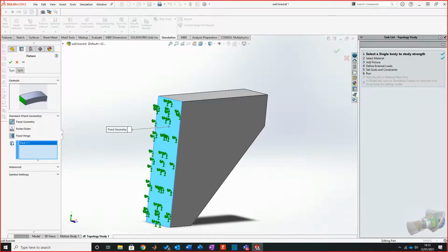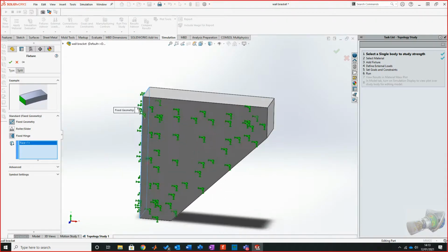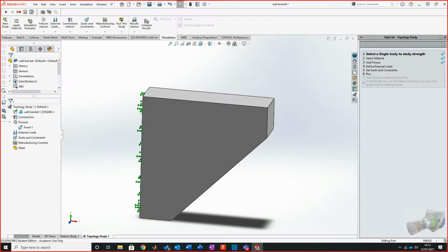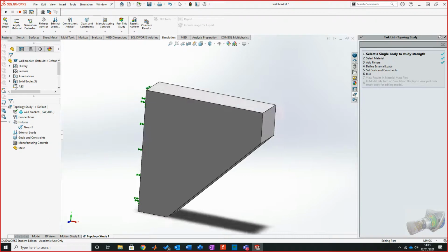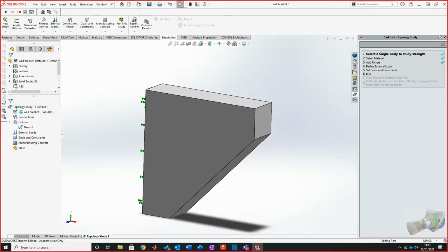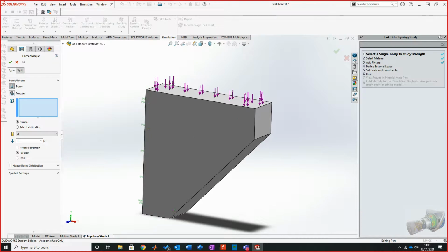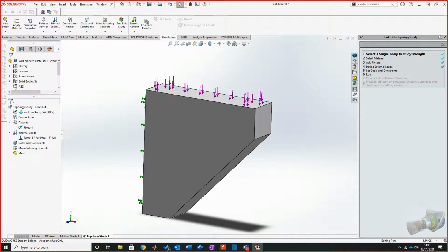Granted, for this example, it is very, very clumsy what I'm doing, because really, if you think about it, we'd need a hole, wouldn't we, to actually act as the mounting point. But for what I want to do here, it does show that process that it goes through. So then I'll go loading, force, and let's go. I mean, it's ABS, so I'm going to go 150 newtons. Maybe, well, I'll go more afterwards, but this is a good start.